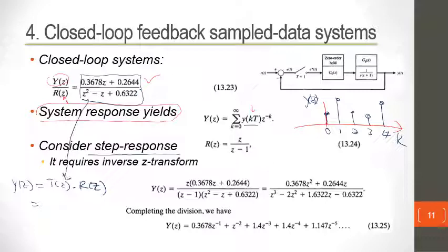We substitute that, and if this is a unit step from the table, we know the unit step will have this as your R of Z. You multiply these two, and this should give you something like this. We have the Z at the bottom here and the Z minus 1 here, and this belongs to the T of Z transfer function here.